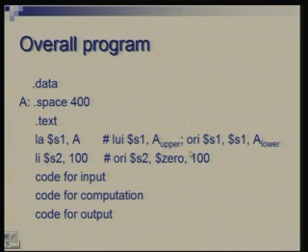And this is what we had learnt in the last lecture, that loading a large constant into a register requires two steps. The first step loads the upper half, the next step loads the lower half. So, the two halves of the address I am denoting by A upper and A lower. A upper is loaded by the LUI instruction into the upper half of S1, and then this OR instruction simply superposes the lower half into the right portion of the register.